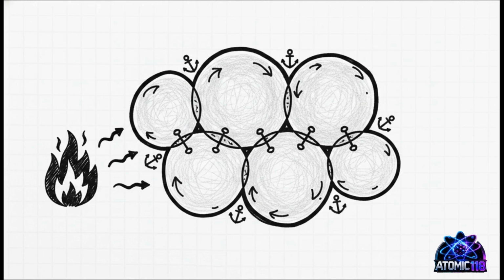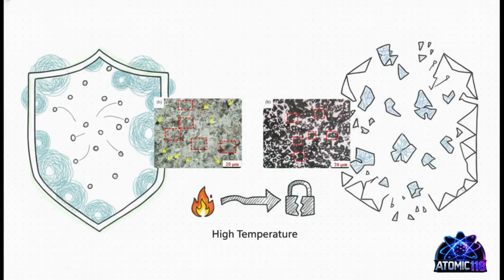The only way those grains can grow is if you push the heat so high that these vanadium anchors completely dissolve into the matrix. As you can see by comparing these different conditions and magnifications, controlling the dissolution of these microscopic anchors comes down entirely to hitting the exact right temperatures. When the heat treatment is dialed in perfectly, we get this beautifully uniform distribution of vanadium grains, along with a tighter network of M6C molybdenum structures.